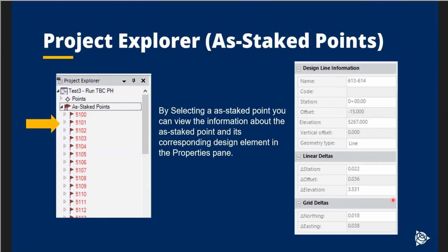However, what happens a lot of times is people go out with some search coordinates for, say, a boundary survey, and they go out there and they start looking around and they load this CSV file that's search coordinates, and they go out and find the property corners, maybe even they calibrate to them and they search for them, but every time they stake it, they might store it in the field. They might store that point as an as-staked. And when that happens, it locks these points down.